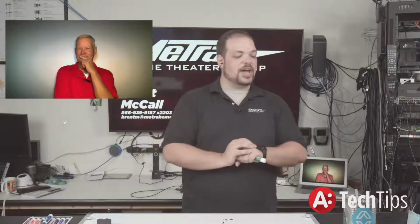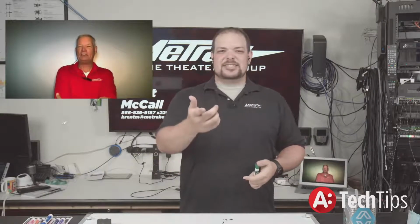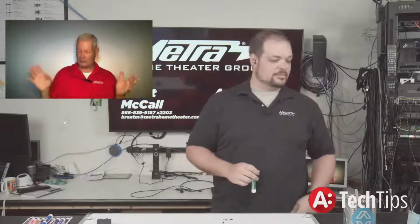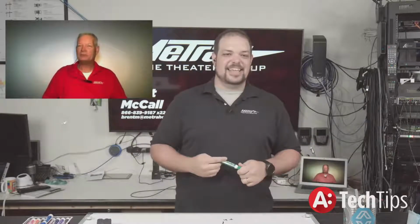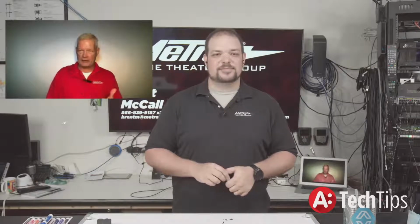He says sometimes you have to use ARC. Toslink does not support Dolby Atmos. That is absolutely true. ARC doesn't support Dolby Atmos either. ARC does not, eARC does. Correct. And right now, to the best of my knowledge, I could be wrong, eARC is not supported on extenders yet. Yet. So stay tuned, of course. I do quantify that with yet. It's a very big yet. Again, stay tuned as we come up with new products and eARC stuff you can do on an HDMI cable.